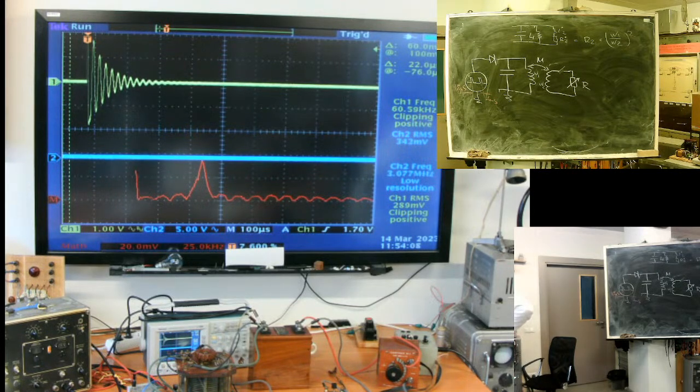As an example, a power supply with quasi-resonant characteristic. With no load regime, you will have one resonant characteristic. When you add a load, the driver of your quasi-resonant power supply should change its frequency to remain quasi-resonant. That's why a feedback coil is mandatory for such kind of supplies. Or I'm speaking about PWM type of power supplies.